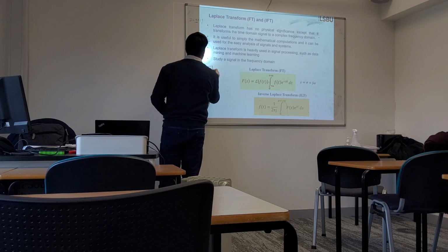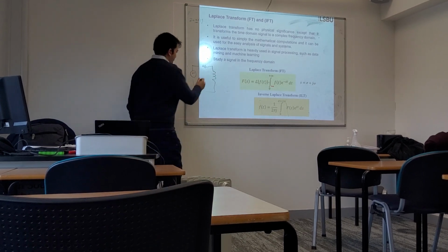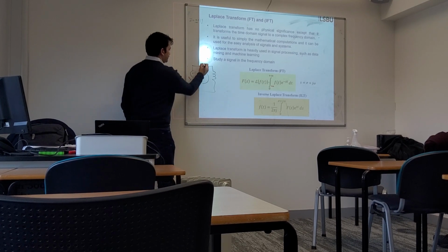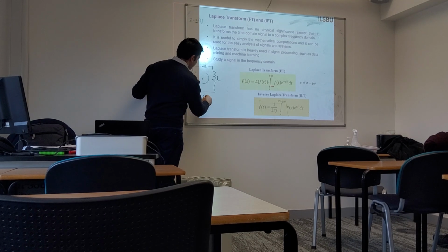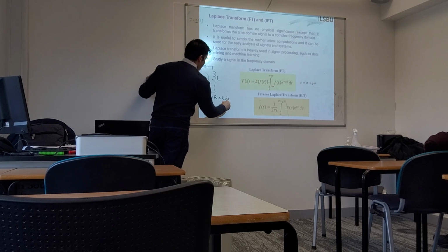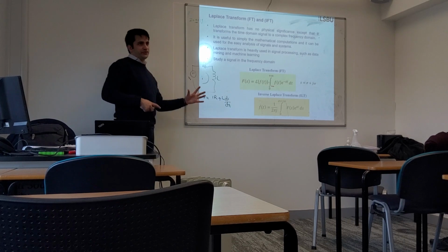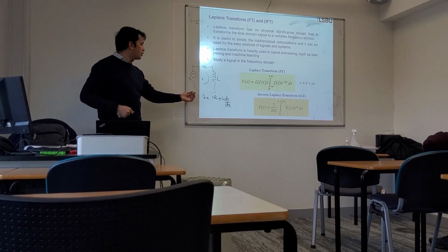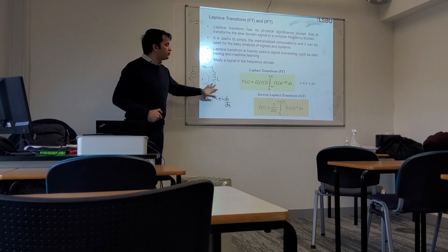So if I have a resistor, if I have an inductor, you all know this, right? Okay. And I know current is flowing in this circuit. If this is Vs, this is R, and this is L, and I want to write the equation, this would be Vs equals I times R plus L di by dt. True, right? So this is the equation for the circuit. Now, for analyzing this circuit, it's very important that I find this current I, which at the moment I don't know. So I need to solve this equation.